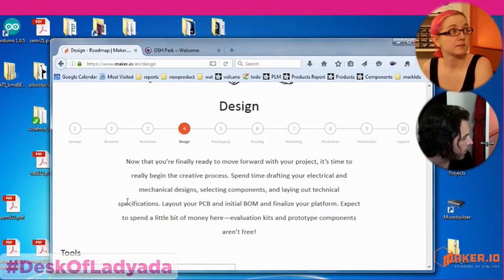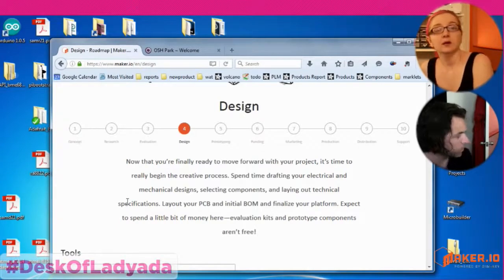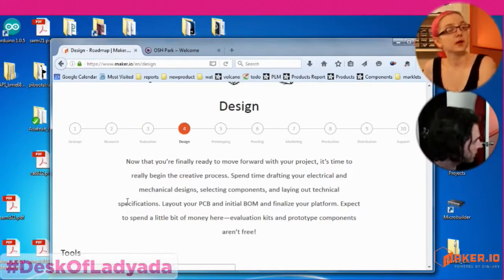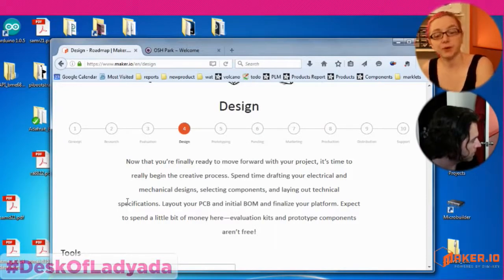Can you think of another example that burned into your head? Is there a past part that you remember that you were using or about to use, and then it was yoinked away from your design? There's definitely been components where you have extremely long lead times, longer than expected. This is where going to the DigiKey site and making sure it's in stock, seeing what the stock numbers are, and if they have lead time. And DigiKey will actually, if you call them and ask what the lead time for this part is, they'll tell you. And that's really important, because if you have a really great part but the lead time is 16 weeks, you're SOL.